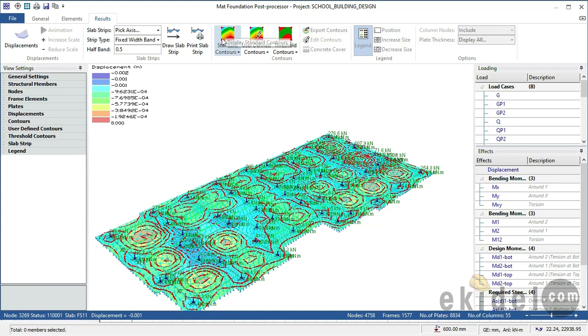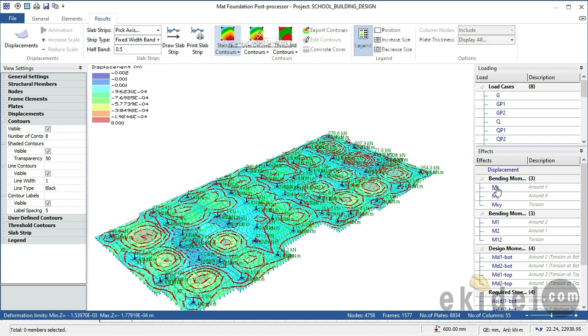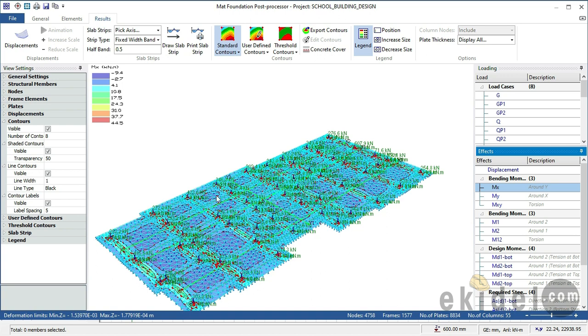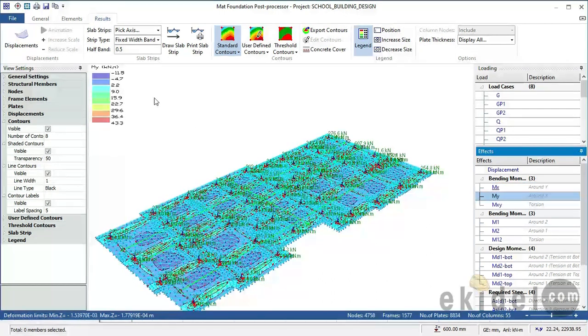So once you have clicked on this place and then begin to click here, as you can see, I'll click here, and then once I click here, I'll allow it to load into this model here. So whatever thing you click here, you have to allow it to load. I'll click again on the next one, and I will allow it to load. Now put your eyes here, you'll be seeing the values of everything we are clicking here. Right now we have clicked on the MX and on the MY, and you can see the value of the moment at Y and also at X.